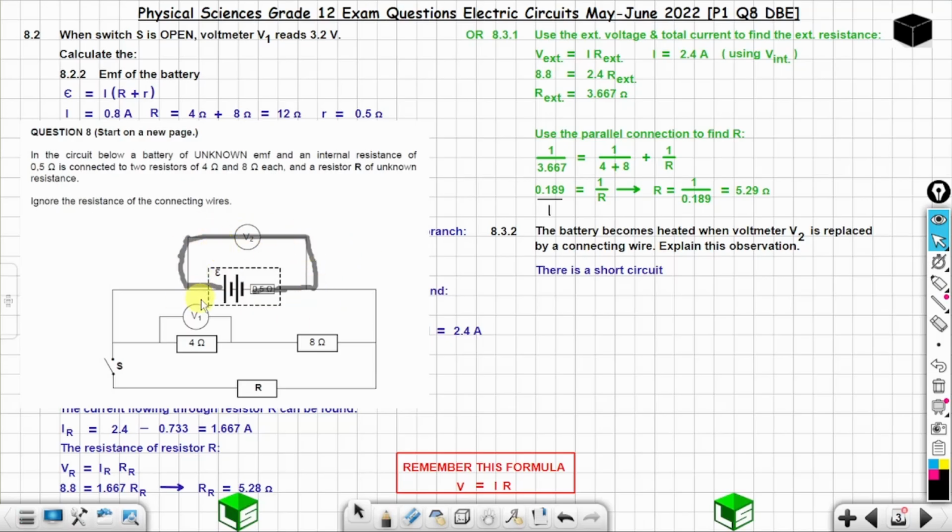You are creating a parallel connection. Remember, in parallel, when you are creating more branches, you are reducing the resistance, while increasing the current. So the total resistance is decreasing, and whenever the resistance is decreasing, the current will do the opposite. So the current delivered by the battery is very high.